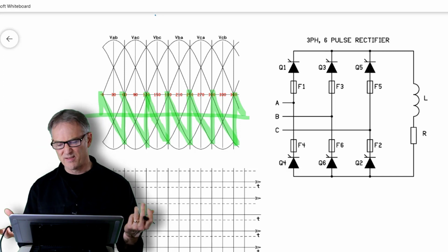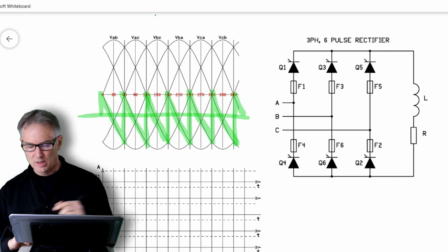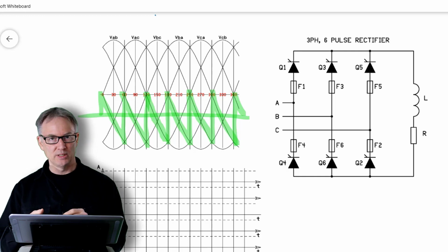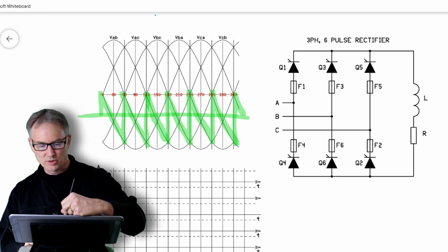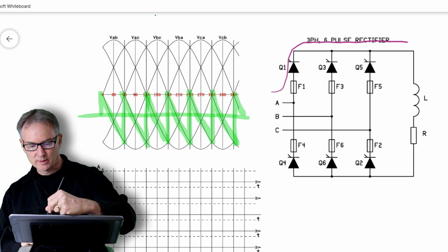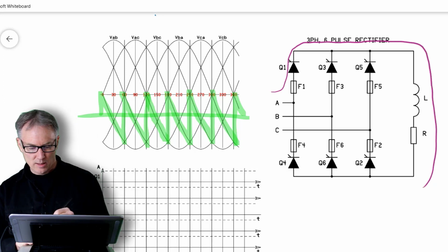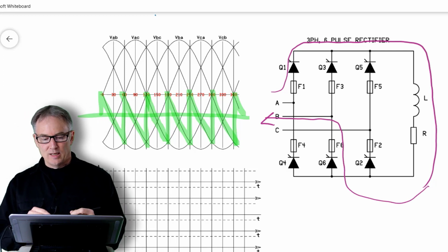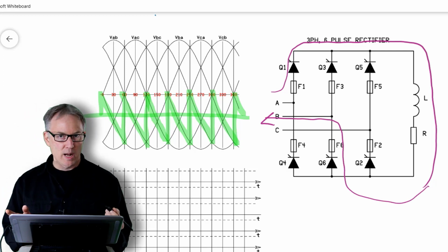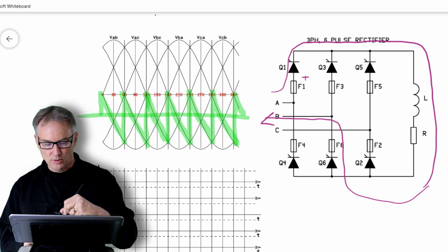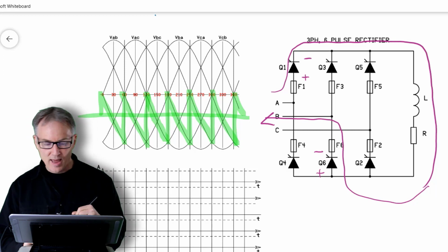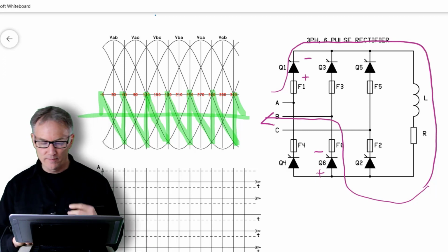So how can I have a negative voltage? Well, if you have a highly inductive load like I'm showing here in this picture, at some point in time, let's say your current's coming around like this, and we'll just say that at this moment in time it's coming back on phase B. SCRs have to be forward biased to keep conducting. So obviously the polarity on the SCRs is going to be like that, otherwise they would be shutting off.